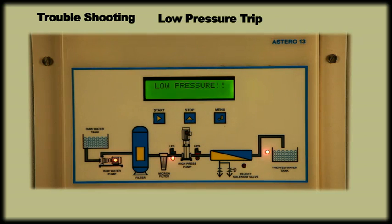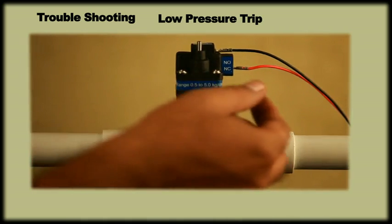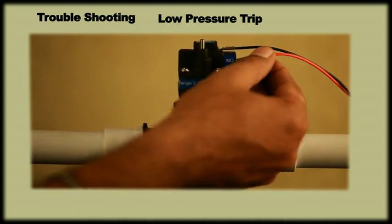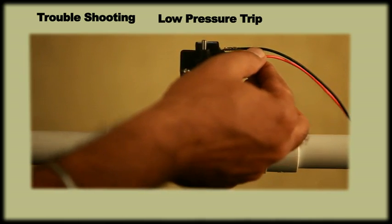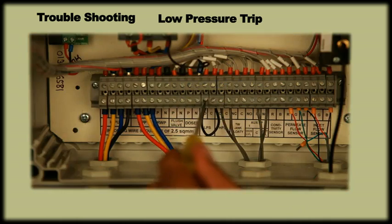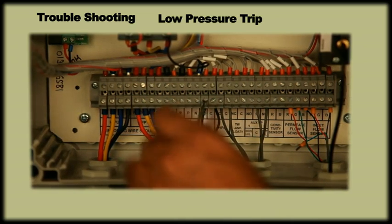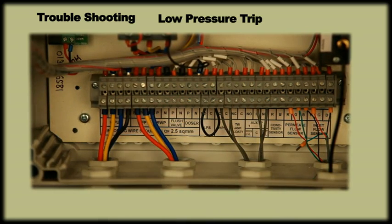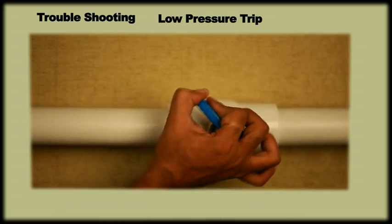If the display shows low pressure trip or message, first check whether a low pressure switch is installed in the line. If yes, ensure that only C and NO of the pressure switch is connected to the panel. If not, connect the low pressure switch in line or bypass it by shorting C and NO terminals. If actual pressure in line is lower than the set value, then increase the pressure.